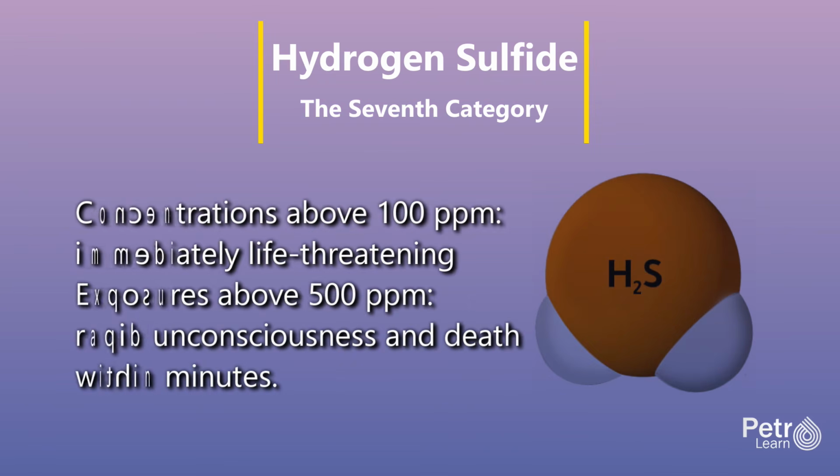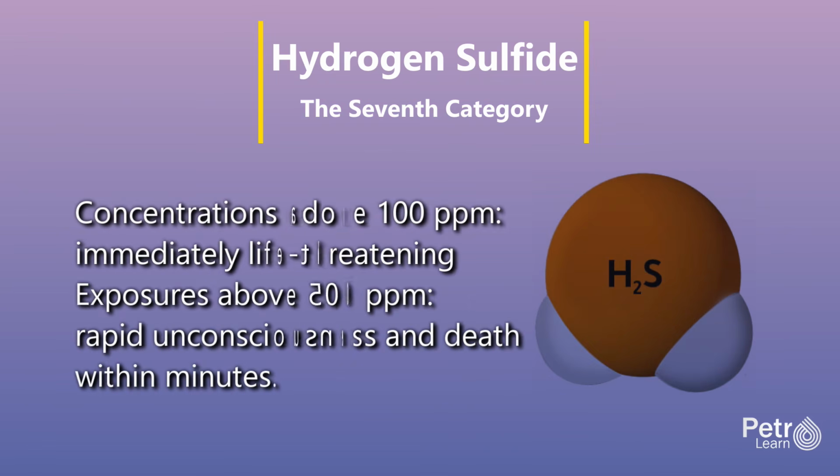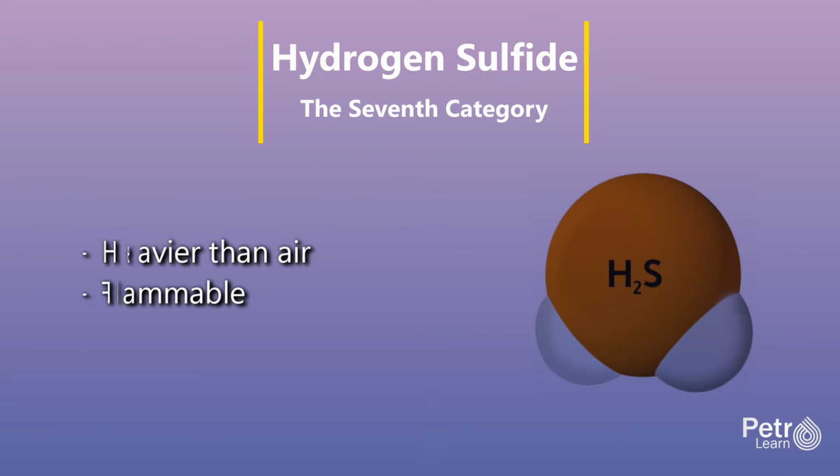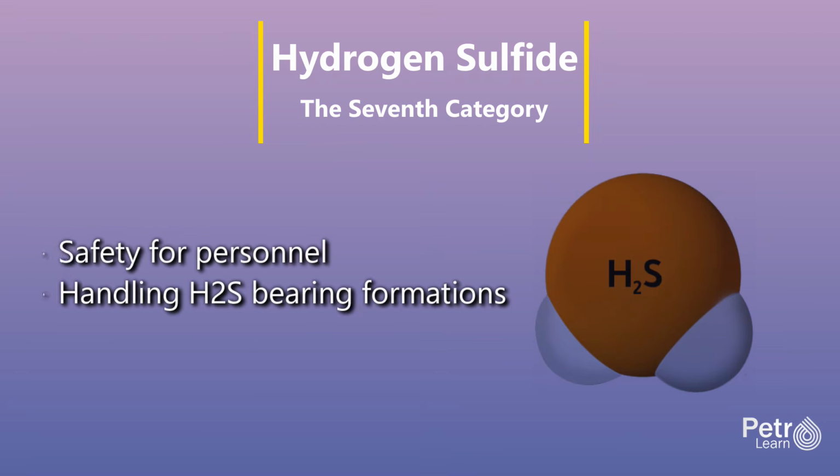Concentrations above 100 parts per million, or ppm, are immediately life-threatening, and exposures above 500 ppm cause rapid unconsciousness and death within minutes. H2S is heavier than air and accumulates in low areas. It is also flammable and forms explosive mixtures with air. When H2S is expected, extensive safety procedures are implemented.